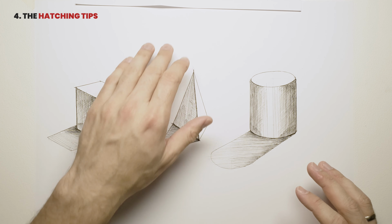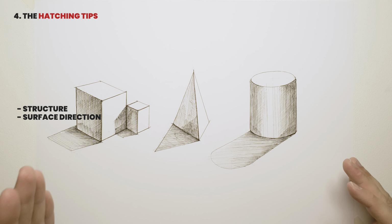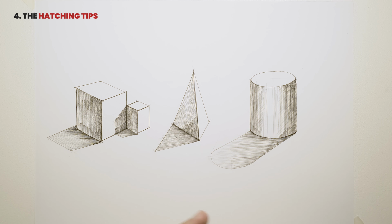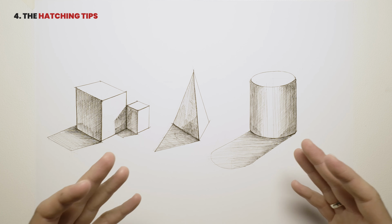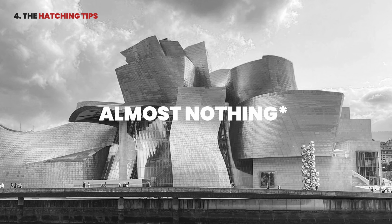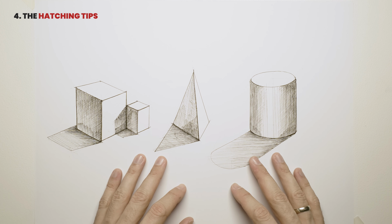I would like to just cover a few points about the proper hatching, the structure and the direction of the surface. It's really important to keep in mind that in hatching and cross-hatching the architecture, to use the vertical hatch. It's deadly important because it makes your building look like a building. The majority of the buildings in the world have got vertical elements to them. Of course, there might be some buildings of, let's say, Frank Gehry that are really irregular and have absolutely nothing vertical to them. However, hatching them using vertical lines is always going to work okay.